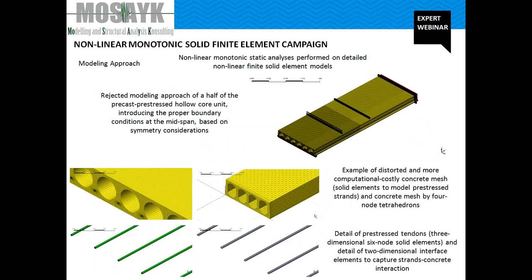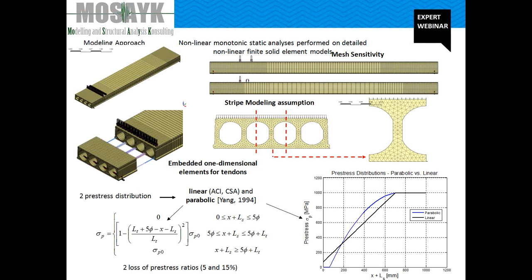The next slide is an example of our three-dimensional model using Midas FEA, using 2 different types of mesh, depending on the shape of the void in the hollow core system. To predict the brittle web shear failure mechanism, the total strain crack model, developed along the line of the modified compression field theory (MCFT), was adopted.